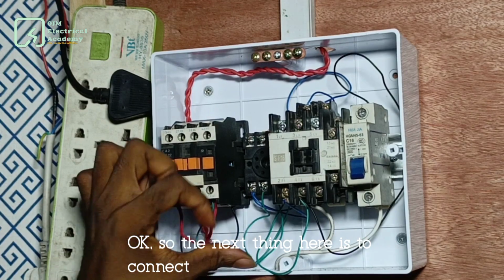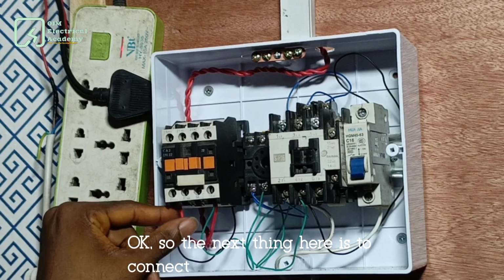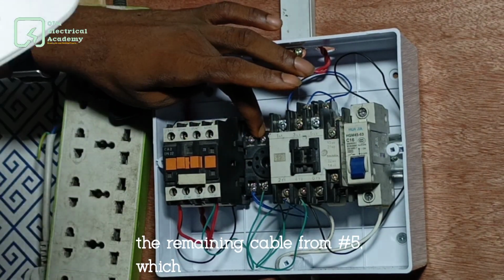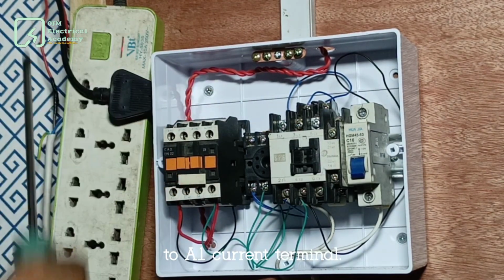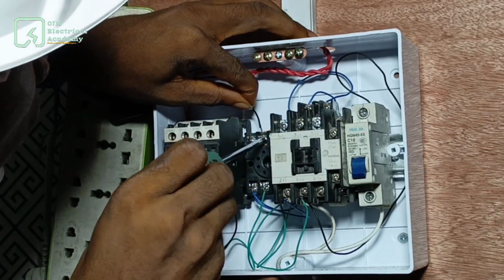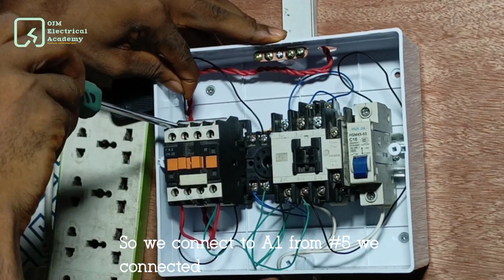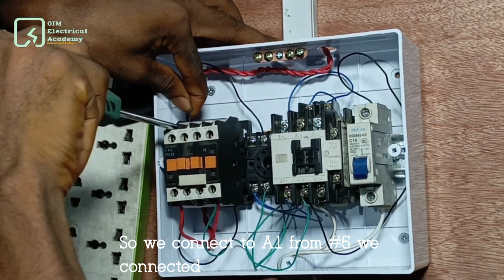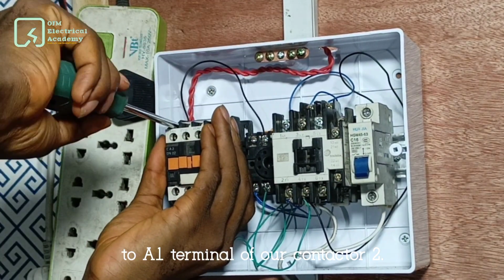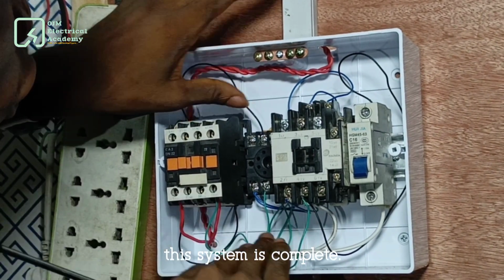Okay. So the next thing here is to connect the remaining cable from number 5, which is normally closed, to the A1 coil terminal. So we connect to A1. From number 5, we connected to the A1 terminal of our contactor 2. So having done that, this system is complete.